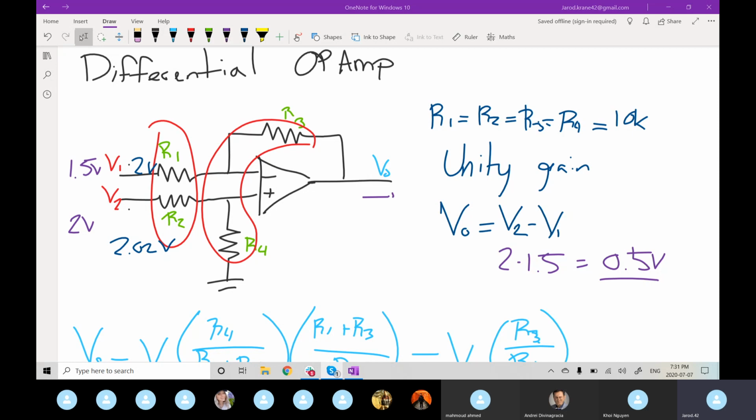Braden is actually using it in the high voltage board for the high voltage measurement system circuits. We are taking our 168 volts and stepping it down to 5 volts so that we actually have circuitry that can read it.